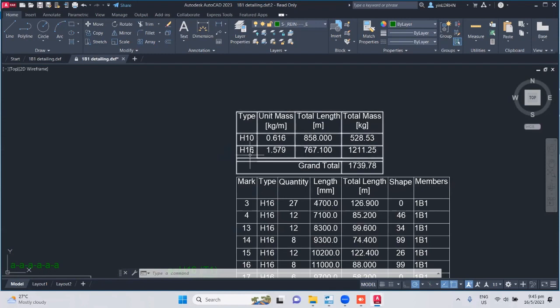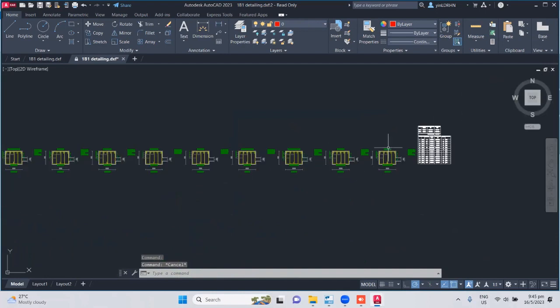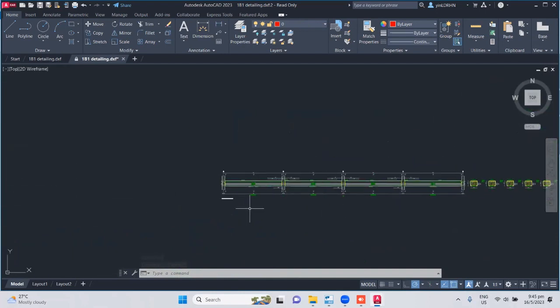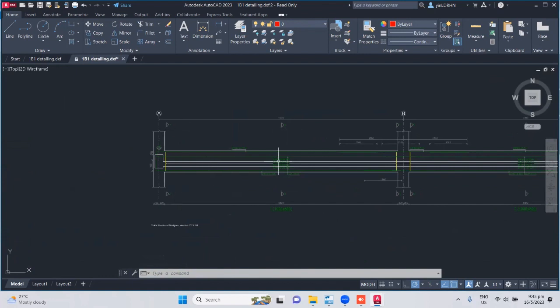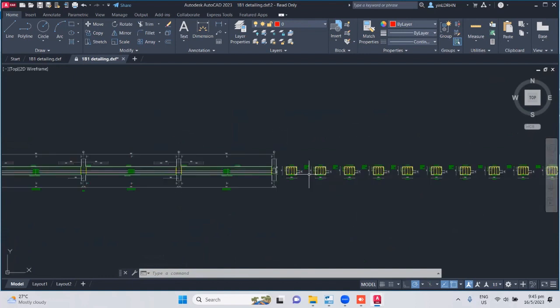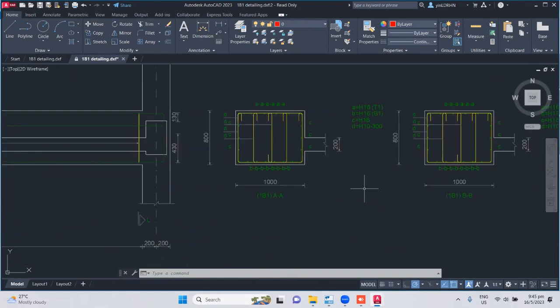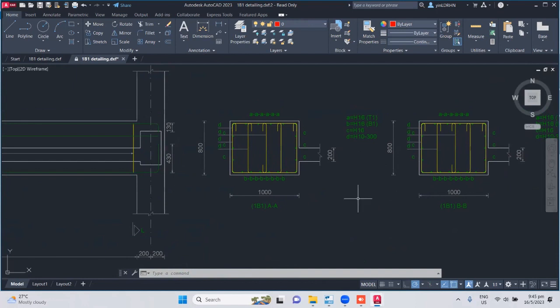Also, it has given the summary of the rebar quantity. How much H10 rebar? How much H16 bar? Okay. So they also give the number of sections, right? Basically each span has 3 sections, left, middle, right, right? Actually it's a plenty of sections. You don't need many, right? You don't need to repeat the detail. You can delete them. You may provide 1 or 2 sections. That's enough for your drawings.